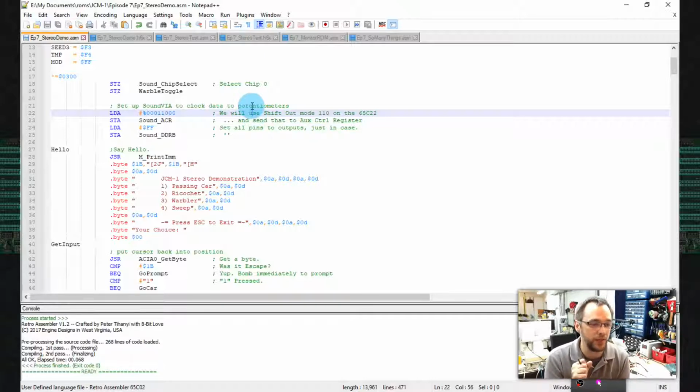And then this is the wonderful asynchronousness of this. Just like the sound chip, when we tell the 6522 to send something out on the shift register, we can tell it to send it out and then go do something else if we want to. If we were using the IRQ line, I could go tell it to do something and go do something else, and then just wait for the IRQ to come back. And when the IRQ comes back, then I can deal with it: I was just doing this thing and it's done shifting a byte, so I can go shift another byte. That's the cool thing about that.